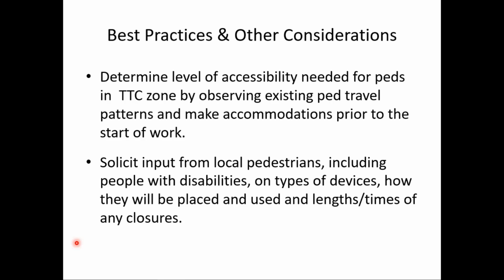Determine the level of accessibility needed for pedestrians in the temporary traffic control zone by observing existing pedestrian travel, and then make accommodations prior to the start of work. Especially on long-term projects, get input from local pedestrians, including people with disabilities.